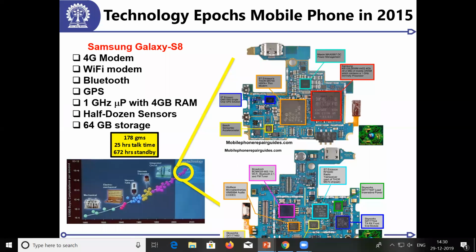So when there is a lot of digital signal processing happening, there is a lot of switching happening, and that affects the analog circuits. And as the analog voltage is reducing with nanometer technology, we call this crosstalk, which means some activity coupling to another one, and that affects the quality or the fidelity of the signal that we are receiving. Okay, so just to give you a perspective, I just went over a few more slides.